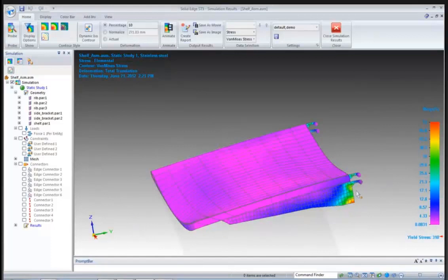This is our area of concern. The principle says that the stress and the displacement in this area will be valid, but we just can't look at it in this area. I hope that makes sense. When you're thinking about what your area of concern is, you want to make sure that everything in your area of concern is included. So we're not going to say 51 is our maximum here. We're going to say the stress in this area is low enough, in the 5 to 10 range here, that it does not exceed our yield stress. And you'll see it's actually way under our yield stress.